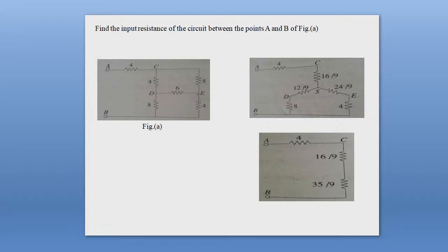CDE portion in the second figure. And finally, you simplify that second figure because you see there are two parallel combinations of resistance between the A and B terminals, and you calculate the equivalent resistance. Finally, you will get a circuit which has three resistances in a series connection. So ultimately, the sum of these three resistances will be the value of the resistance between A and B. Okay.